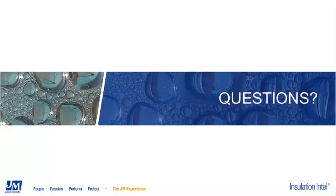Let's start with the insulation material being used. And we talked how different materials have different thermal conductivities. That's one aspect of driving the thickness. The next would be the design criteria. Is it code compliance all you care about? Maybe in Vegas that's all you care about because it's never humid enough to worry about. Or maybe even in Vegas there's a desire to achieve some degree of condensation control on the few times a year that it's humid there. So you'd have to select your design criteria. Is it code compliance only? Is there a heat gain limit? Is it condensation control? And then you have to start examining the climate and the pipe size.